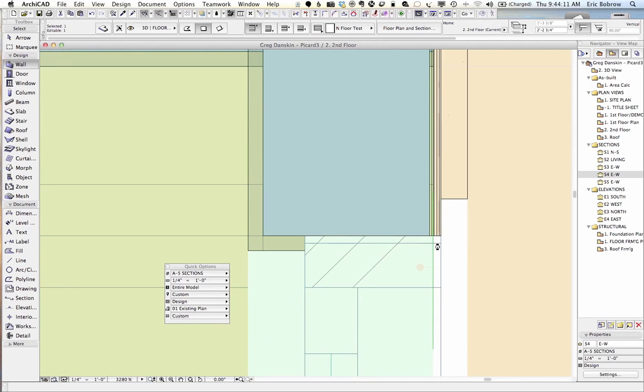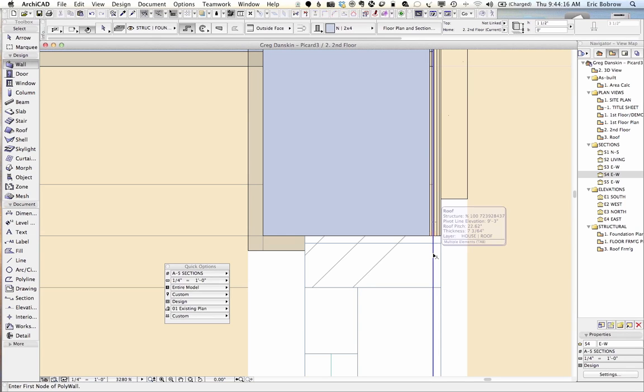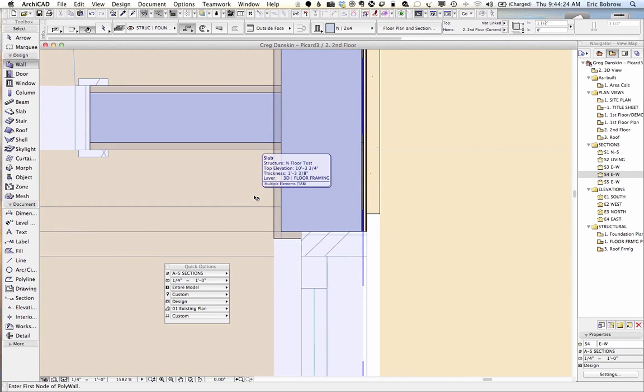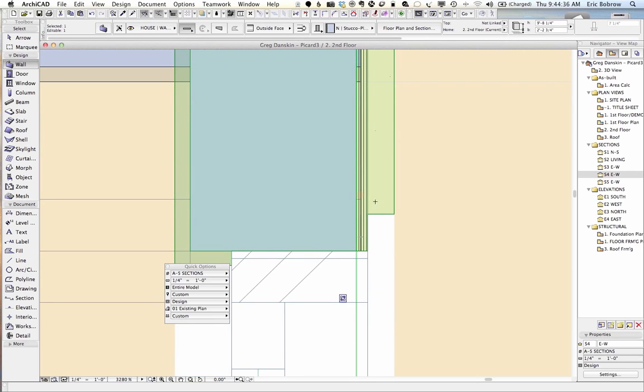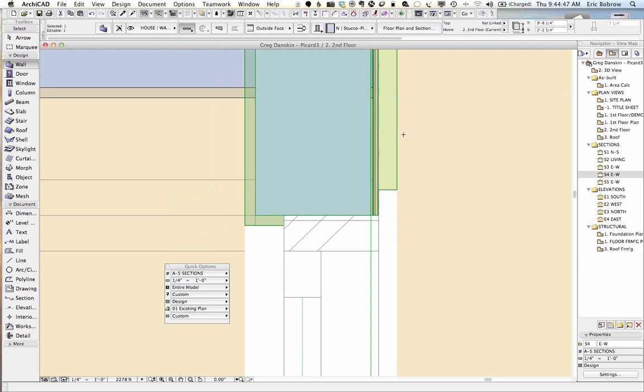No, but that didn't snap quite right here. But I just need to make sure that's the roof. That's the slab, which is the new test. All right, so the wall here. Okay, here's your framing line. And so what's outside here? You've got sheet 3/8 plywood sheathing. And then what's beyond here? Stucco, 7/8 stucco. Okay, all right.